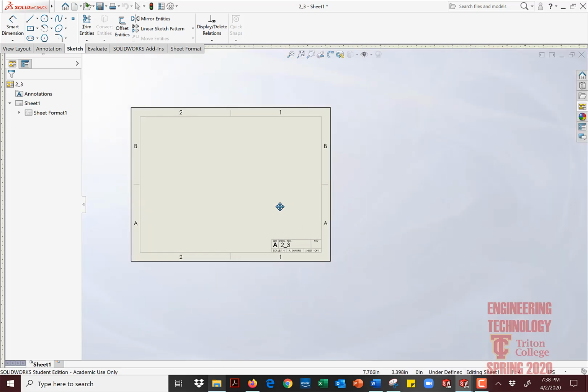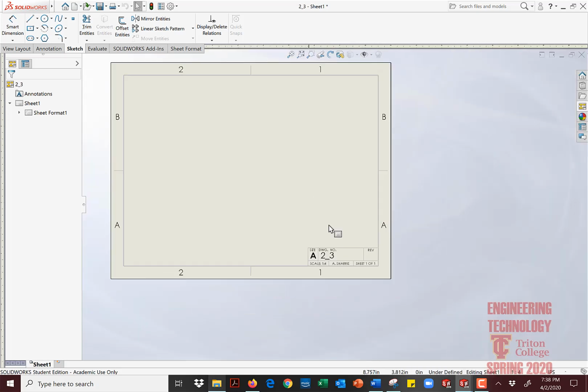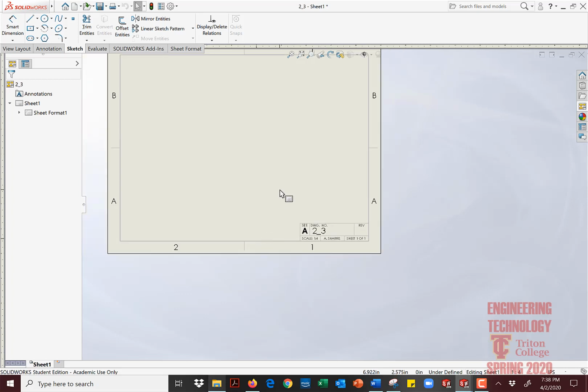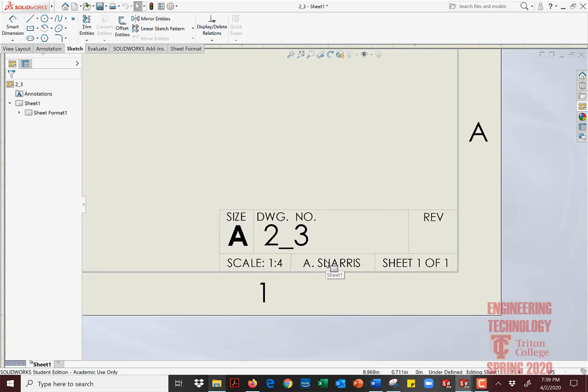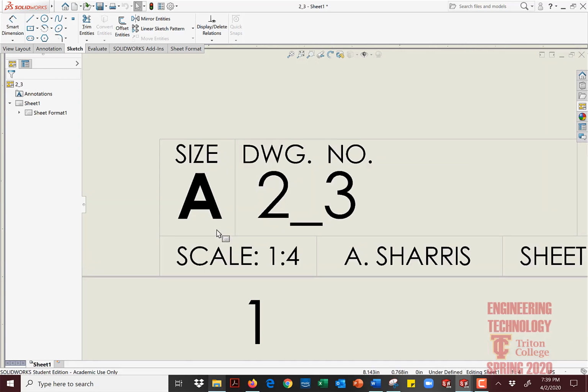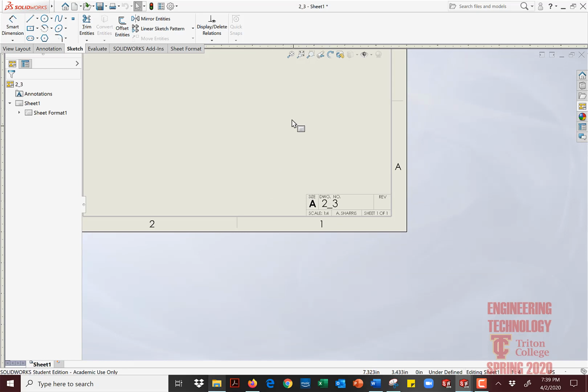And the template, what's unique about it is that it contains a petite corner, in the corner, out of the way title block instead of a massive title block with lots of content. It's a very simplified title block. It'll have the scale, the drawing number, revision for when you need that. Your name needs to be on it, and the sheet. And the size of paper, it's an A-size paper.